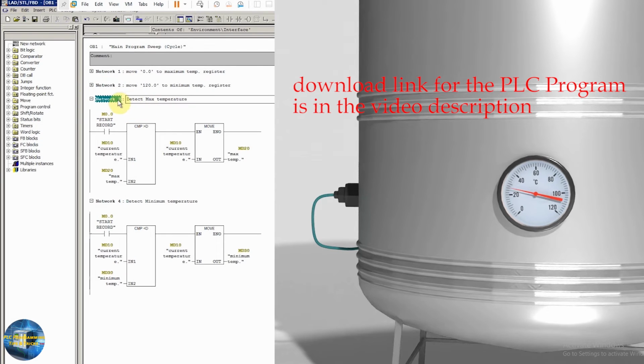In network number 3, we will detect the maximum temperature. The logic is really simple. As you can see, we have an M0.0 start record bit and a comparison command. This comparison command will compare two values: our current temperature value, which is coming into MD10, and the maximum temperature data register, which is MD20. As we know, we have already moved 0.0 into the maximum temperature data register. When we turn on this start record bit M0.0, it will start the comparison between these two data registers.